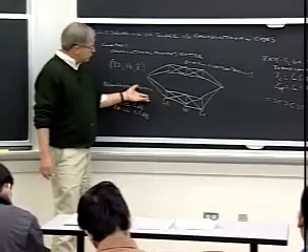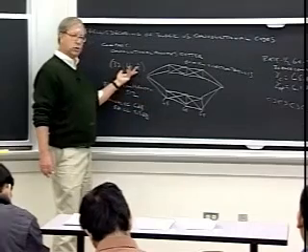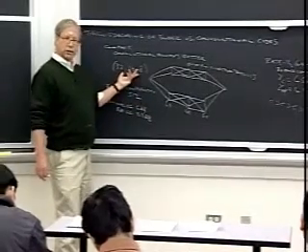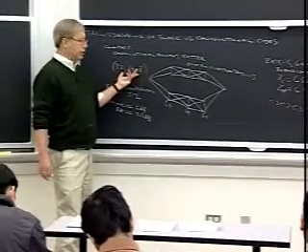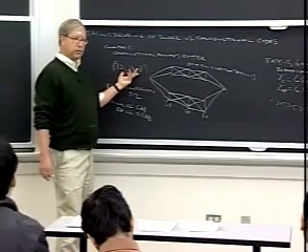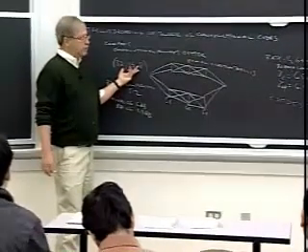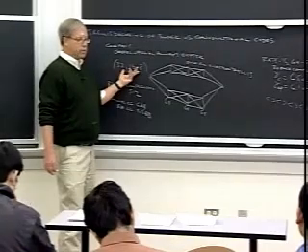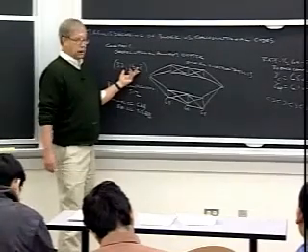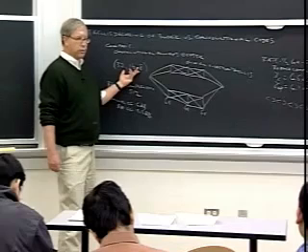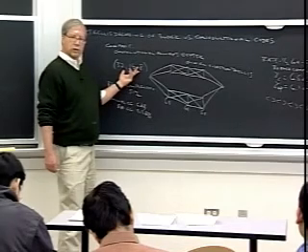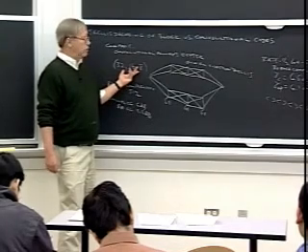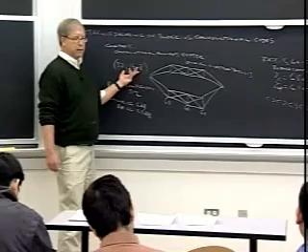But nonetheless, in terms of block code parameters, you're not going to do better than what 50 years of algebraic block coding theory has come up with. So for short block codes of length less than 100, let's say 128, the best we know of right now is to pick a good Reed-Muller or BCH code, find its best trellis, and do maximum likelihood decoding.